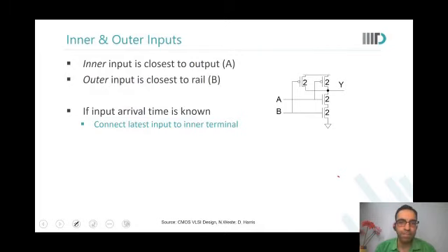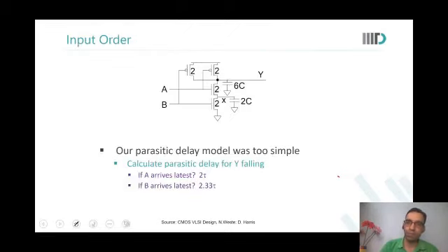Even then, let us look at it like this. Even if it is a rising delay, it was 0 earlier. You took A to 0. So now what is the capacitance that needs to be charged? Only the capacitance on the Y output. Am I right? So what's the stimuli that you're giving? Output was 0 initially, so both A and B were 1.